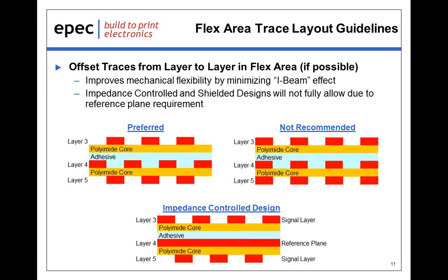Moving on to some trace layout guidelines, specifically in the flexible areas. We always recommend to our customers that traces be offset from one another as you look at the end of the design from layer to layer, if at all possible. And you can see in the first image there, the preferred, where the traces, this is an end view of the circuitry, where the traces are offset from one another.